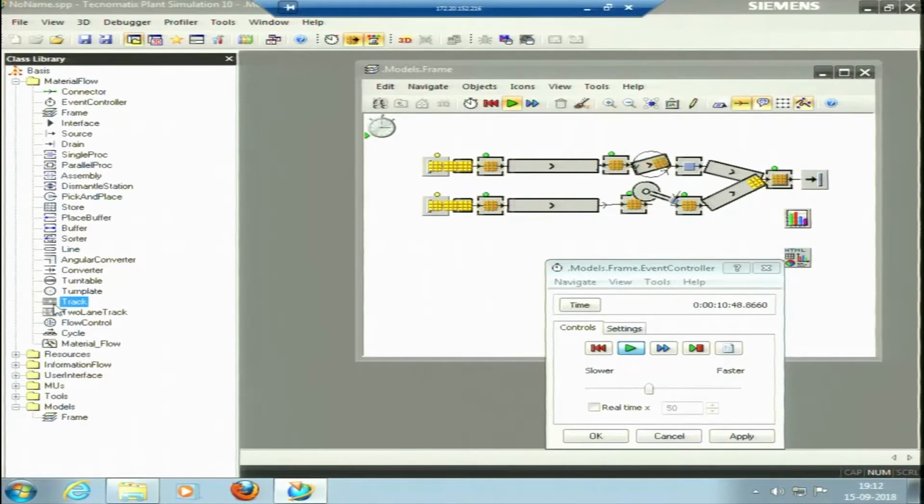So the maximum capacity of the track is defined by its length, and the lengths of the individual transporters moving on it can also be defined. That is, a track that is 3 meters long accepts 3 transporters of 1 meter each. So there can be certain other capacities. We can have certain kinds of track. We can even have a turned track, or a 2-lane track. A 1-lane track goes in only one direction. A 2-lane track can go in one direction and come back from the other side. It is like a two-way road.